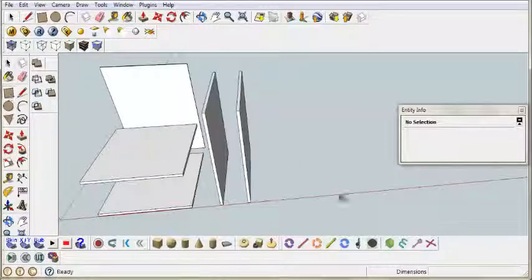Okay, now let's do this again. This time with the rectangle tool again, and then use this as an endpoint. Copy this from the point. Then, since we're doing the front panel, you have to follow this rule. Since we're gonna use doors, we're just gonna make one big door. Let's make the width 598, with a mil on each side as a gap, and then the thickness would be 19 because it's the front door. So here I go, and then push up,